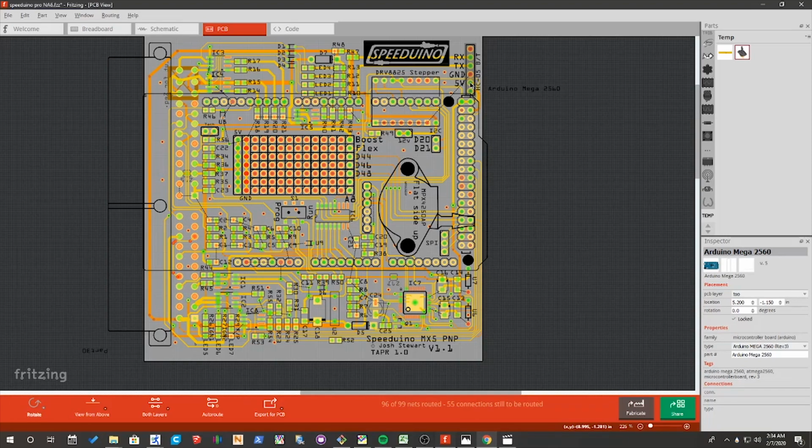And when I checked those on my ECU, what I found was that one of those 5 volt outputs was as low as about 1.3 volts, and the other output was as low as about 0.1 volts, really low, which led me to believe that there was something wrong with this integrated circuit, because it was no longer outputting the 5 volts that it should be.